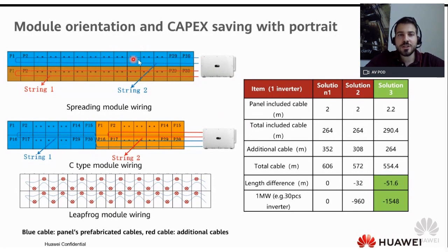It means that each row will get its own cable, and it will be reversed from the back, and you are using quite a lot of cables back to the inverter. But as I mentioned previously, this is actually good for the yield. But if you want to focus on the CAPEX, you should change to the C type, which is not a division made by row, but it is divided by left and right, for example.